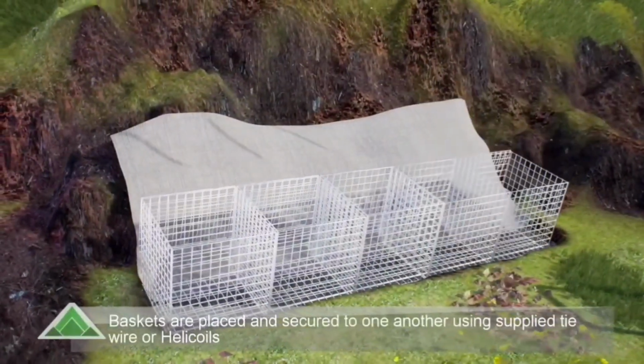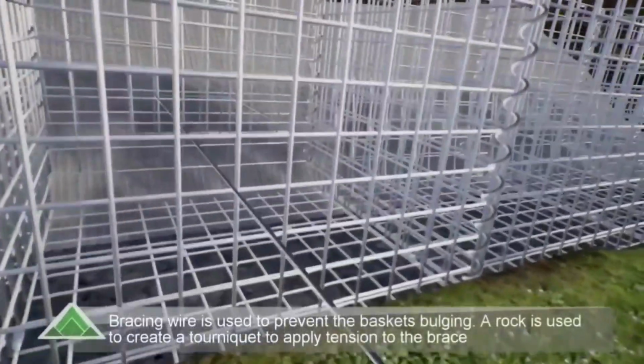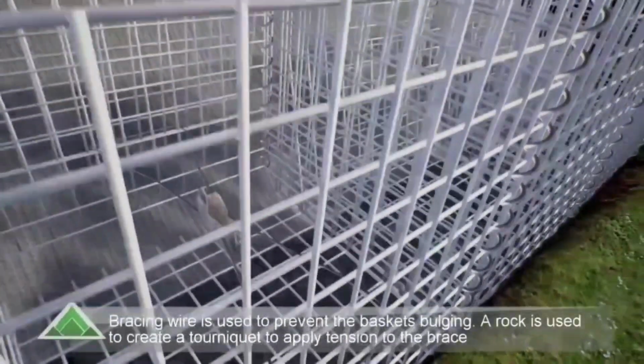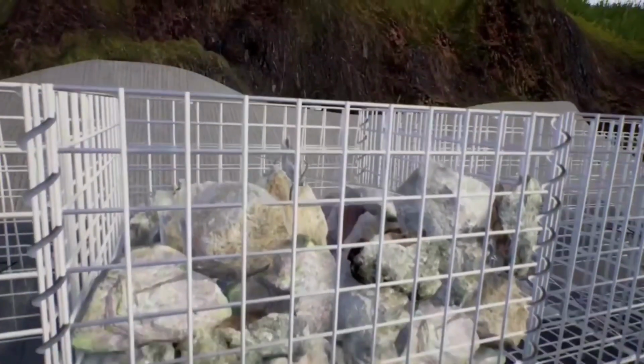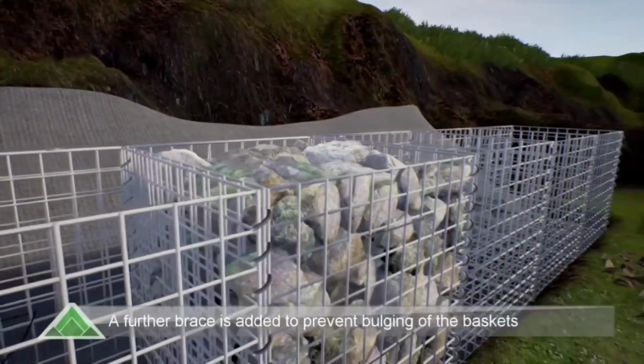Baskets are placed and secured to one another using supplied tie wire or heliocals. Bracing wire is used to prevent the basket bulging. The face of the basket should be hand-laid to create a dry stone wall effect. A further brace is added to prevent bulging of the basket.